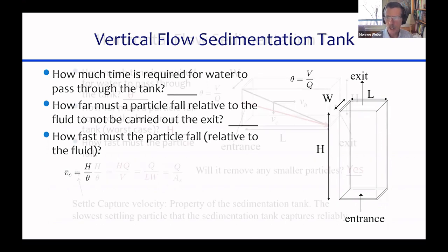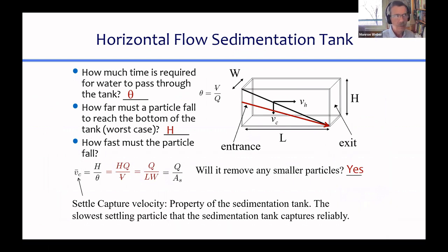And so then you think, well, why don't we go back to this system? Why don't we just put two cake pans on top of each other? Why don't we just make a bunch of small tanks and have them on top of each other? Why wouldn't that work? Right, because if I have a whole bunch of tanks stacked on top of each other and I have water flowing through each one, then I've effectively increased my plan view area. But the problem is I have to figure out what to do with the sludge. Sludge is the problem.